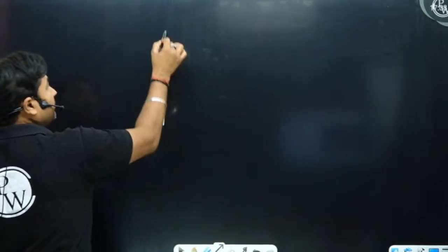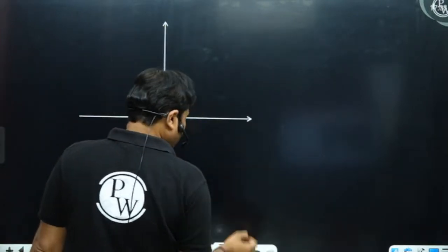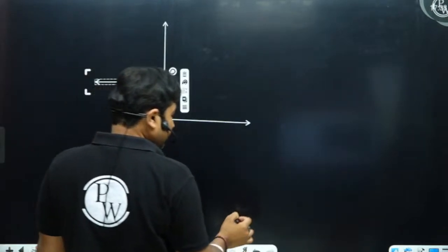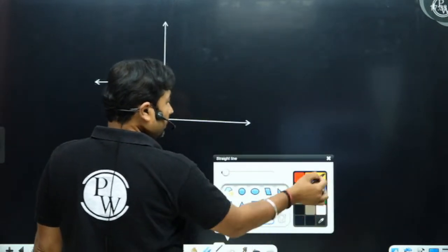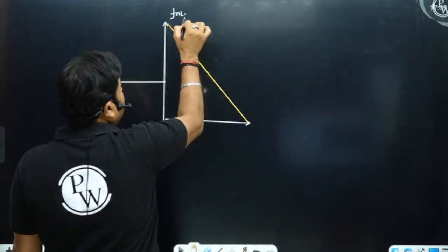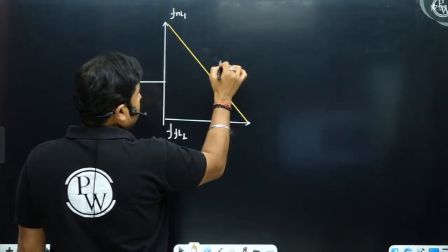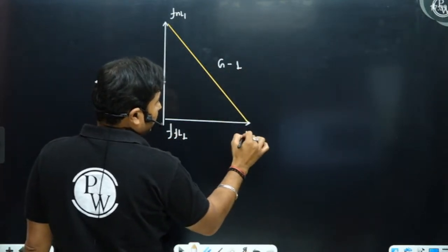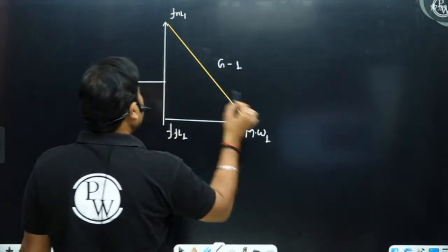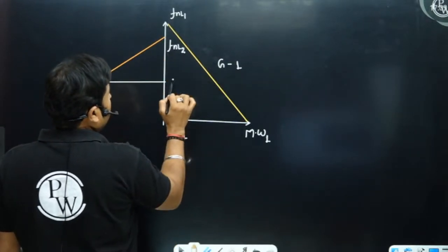See, in case two or more alternators are operating in parallel, they will have different drooping characteristics. Suppose alternator 1 has a drooping characteristic with its no load frequency and full load frequency, with megawatt 1. Another alternator, generator 2, has different drooping characteristics, with its no load frequency and full load frequency.